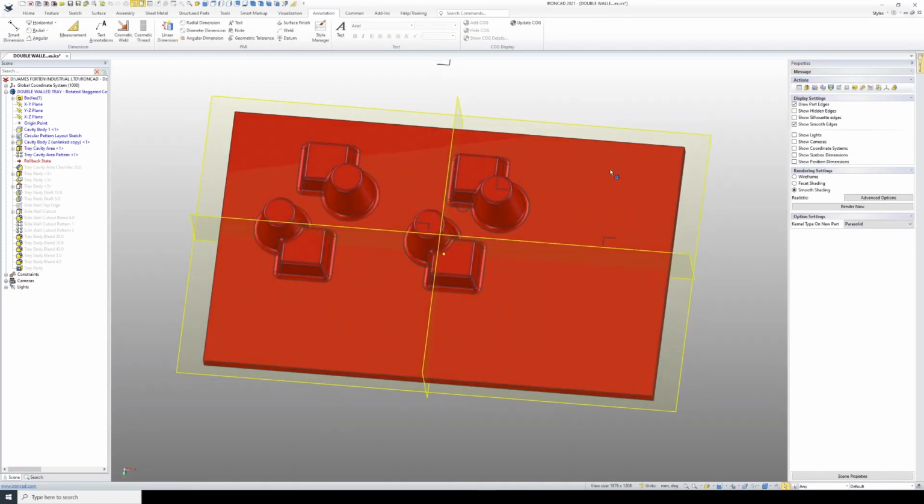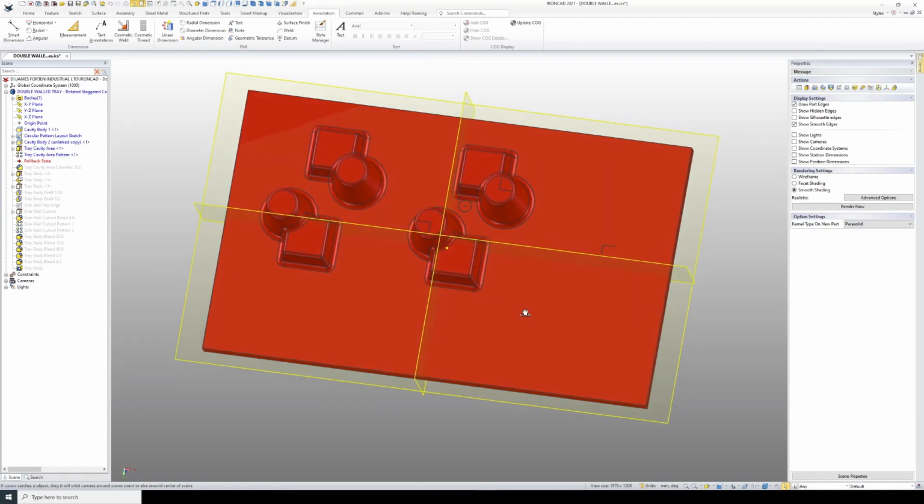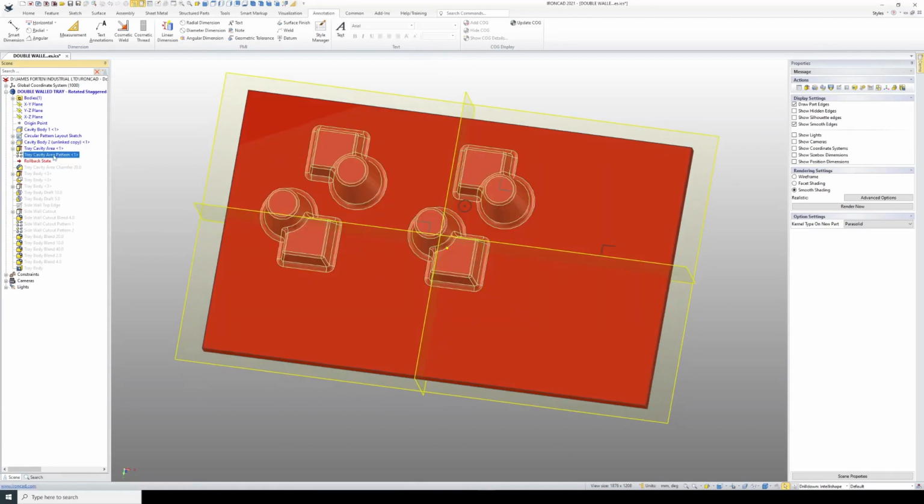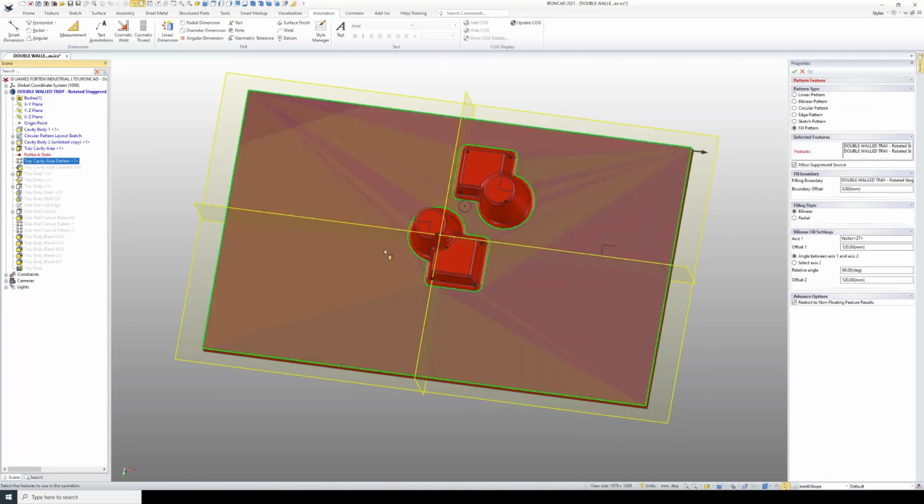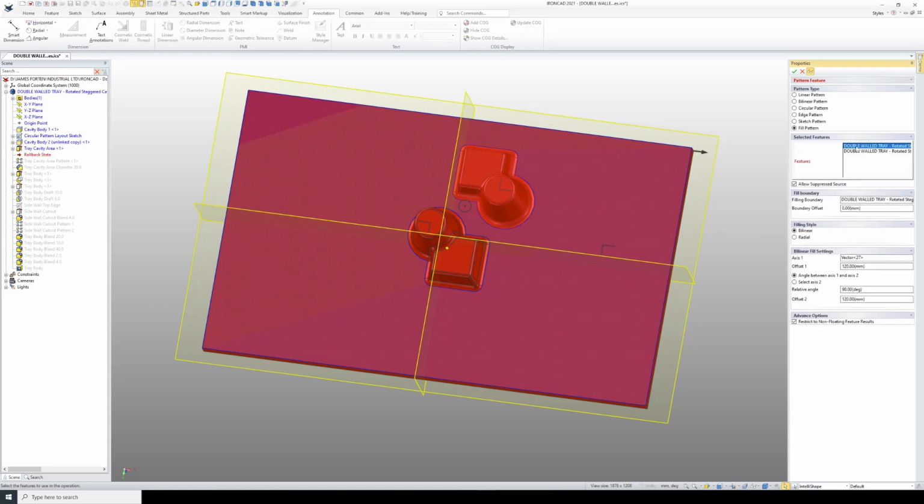It doesn't seem to be populating the area all that well, and the reason for that is that in the pattern it's looking at the available area, and it's looking at all of the items that I've selected, in this case 2 bodies, and it's treating this as a group. It says, well, where can I position this group together, obeying the variables that I've put in. And so the end result was that there weren't many options for where it could put it.